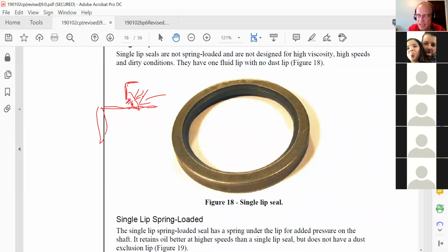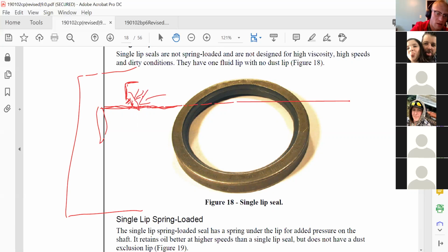The inside one. Mm-hmm. You mean the one inside the drum? The one beside your slack adjuster. Yes, the one in the trailer frame. So I'll extend this all the way over to here. So now I'm saying we're going to put the one in backwards, as in they both face the same direction. So here, this is the side inside the wheel drum. Here is the S-cam head, and we have our brakes and all that good stuff in here, inside the cam tube.